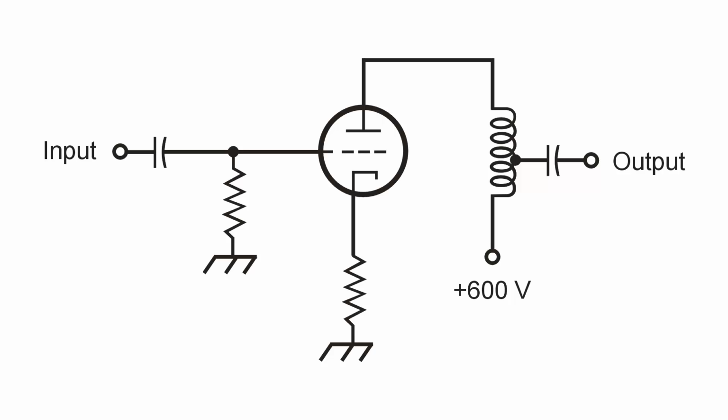But what I'm here to do right now is to explain the function of each individual component in a simple radio frequency triode vacuum tube amplifier circuit. Now, a triode vacuum tube, this is the symbol. This electrode is called the cathode, and it emits electrons, free electrons, which travel through essentially a vacuum, not atoms with electrons missing or extra electrons added, as in semiconductor devices, but an actual vacuum through which electrons travel.